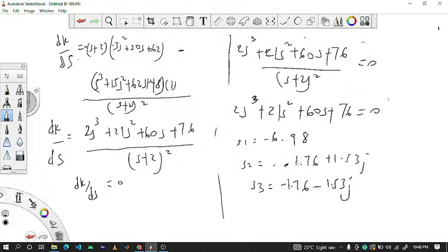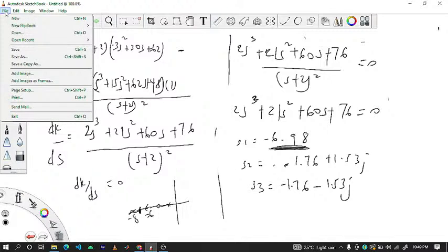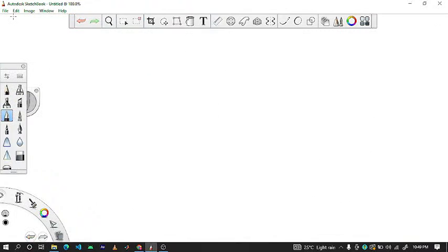And this is why it was paramount or expedient for us to make the rough sketch. See, in our rough sketch, there was a 0 here, right? Then we saw that there was another pole here, another pole here. So we know that our breakaway point will exist here, where here was minus 6, here was minus 8. Our breakaway point will exist between minus 8 and minus 6. So among these values, you can see that yes, our S1 is actually between these two values. So now we can do what we are supposed to do.